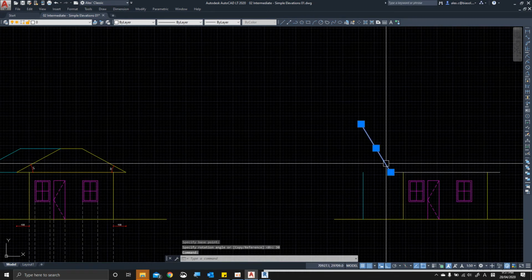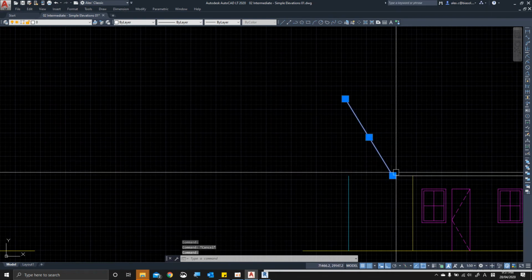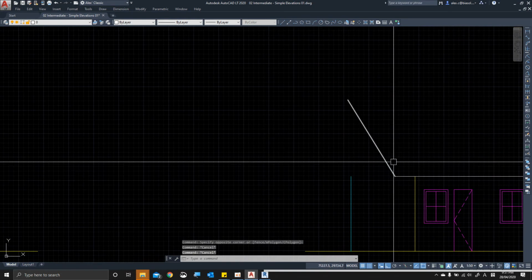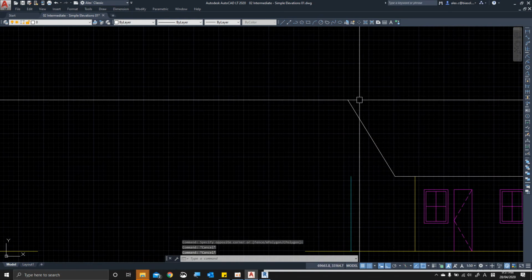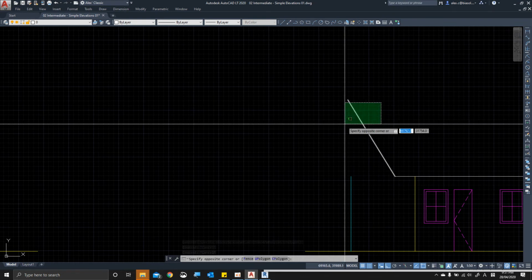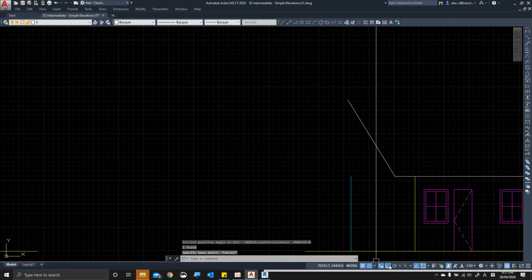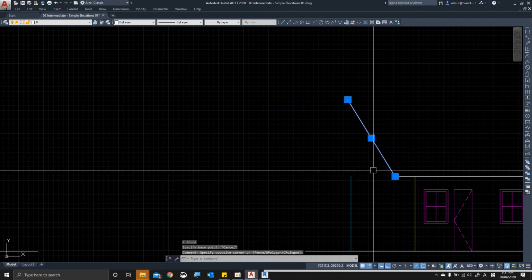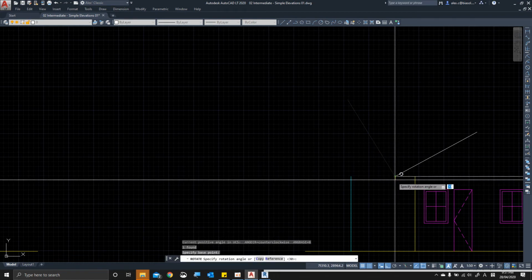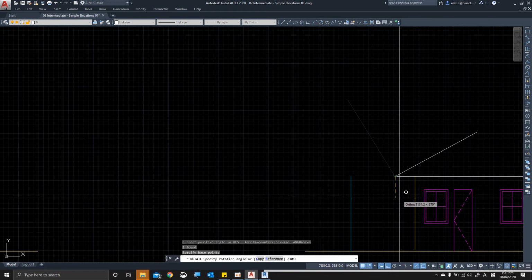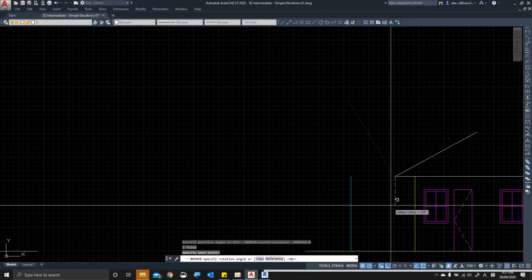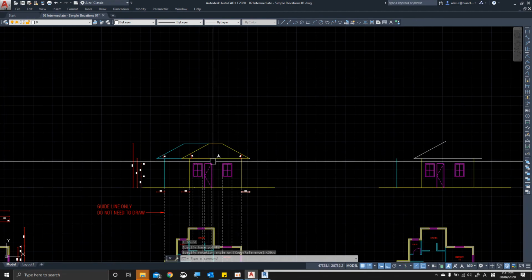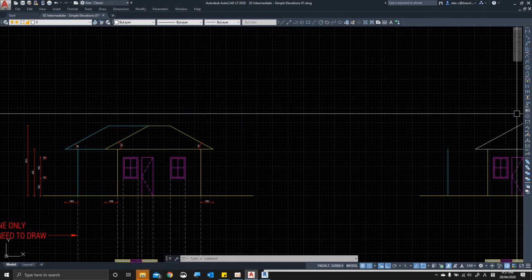Okay, so I just rotate the line and I click this one as the center point, so that's why it rotated to that direction, 30 degrees. With that also turned on, which always moves things perpendicularly, click here, just move your cursor to get that position. So that would also be 330 degrees. Let's just check it.